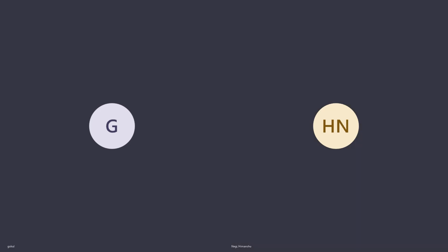I'll let you know what remnant flux is and how to model it in 4.5. I can teach you that. Even in 4.6 they updated something like this, so there is no extra model needed. You can just give the value over here and simulate. That's the advantage of the latest version: you can give the remnant flux on each core and do the simulation. I'll show you how to do it in PSCAD 4.5.